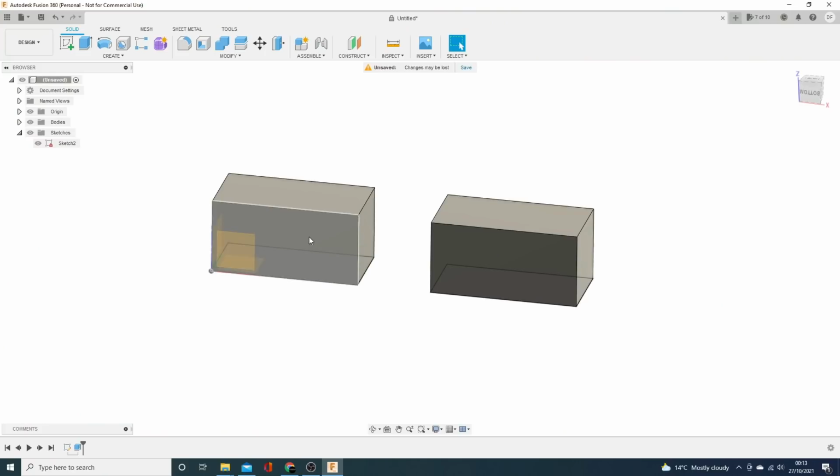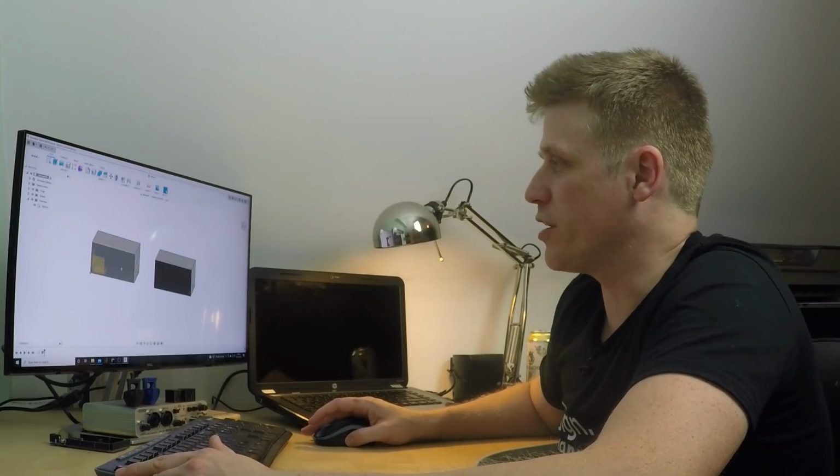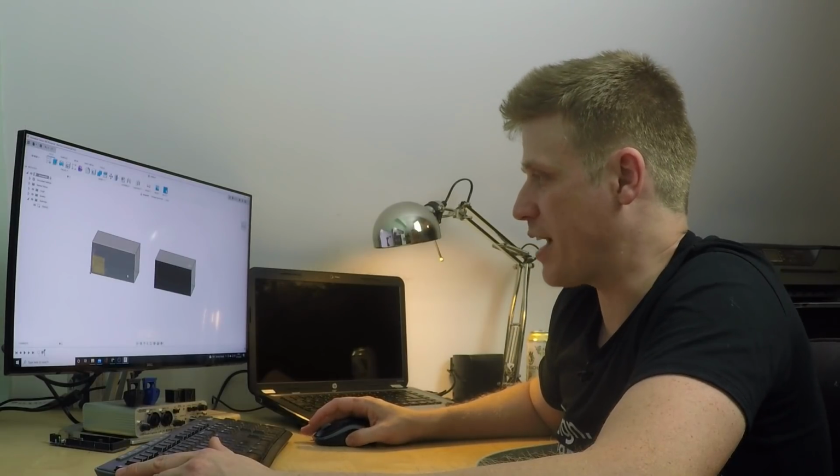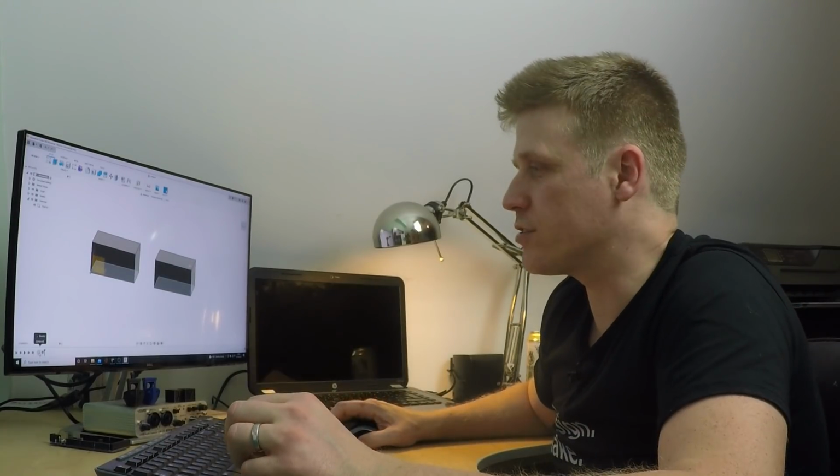I've changed my mind again. Yeah, I know. I don't want this to be 30 by 60 anymore. I want it to be back to being a 30 by 30 by 30 cube. But I want to retain this one as 30 by 60, and I also need to retain that 30 mil gap there. So this is where it gets very powerful, because if I know my key design points are this size plus 30 mil gap plus that, then that's baked into the constraints.